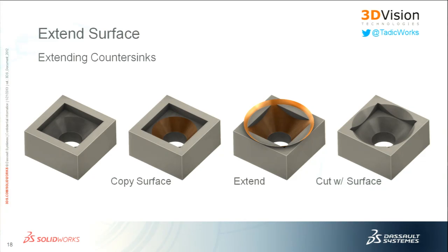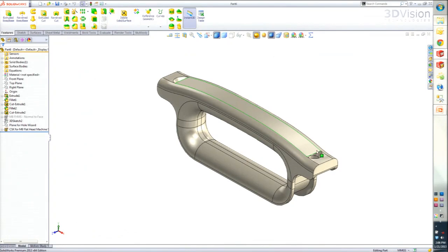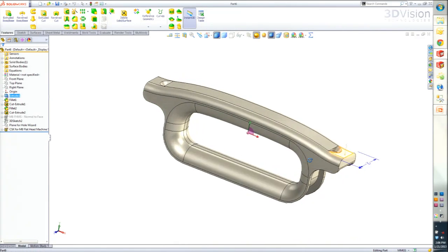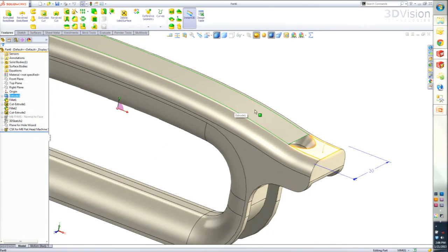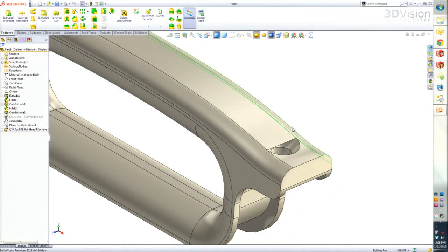So the solid model that I have as an example right here is that we created this hole on this face right here, and it's creating that hole normal to the surface, but it doesn't know that that surface eventually curves up above the initial plane that it was created on and covers that hole. It's not going to extrude cut in the opposite direction, the hole wizard. Unfortunately, we can't use delete face right here because it's a little bit too complicated with all these surfaces converging into a similar area. Sometimes that happens.